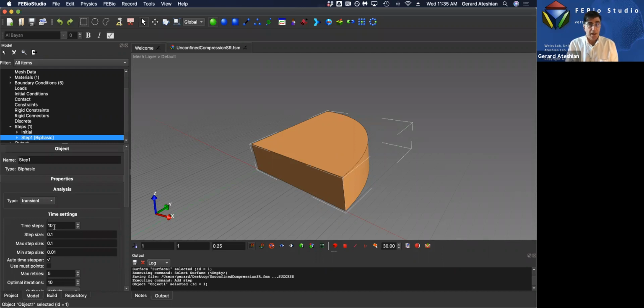Because I'm ramping up displacement in 1 second, I do want my time increment to be 0.1 second by default. This way I can accumulate about 10 time increments during the loading phase, which is very rapid. I don't want to load in 1 second in one single step. So that means that if I want 50,000 seconds, I need 500,000 steps that are 0.1 seconds long to give me a total analysis time of 50,000 seconds.